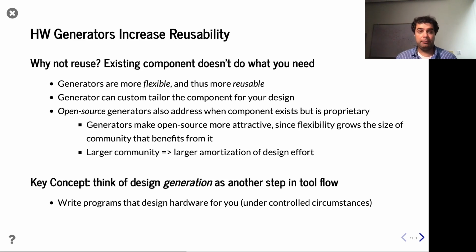And it turns out people have been trying to do this for years, right? And so actually standard practice in many large hardware companies is to already do this, right? They write generators for things like a network on chip, which is a good example. It's a very regular standard process. They might write a generator in something like Python or Java or Perl, and that thing spits out pieces of Verilog stitched together that make the thing you want, right? And that works, but we're going to cover in this course how we can build generators much more cleanly with a language called Chisel.